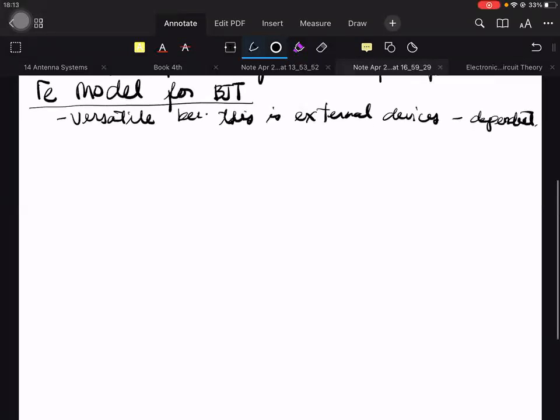So we've already appreciated this idea when we dealt with the stability of the DC configurations, diba, na ato na solve previously, nga voltage divider bias would be more stable compared to emitter bias, and of course compared to fixed bias, because no matter what value of beta we would replace our circuit with, dili kayo maapektuhan ang values sa circuit, no?